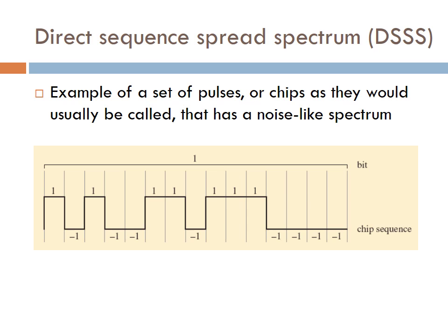Because the sequence spreads the spectrum of the baseband signal, it also spreads the spectrum of the modulated signal. Reception of the data depends on the receiver knowing the codes that are in use by the transmitter and being able to synchronize with the transmitter. I will not explain how synchronization is achieved, but if these conditions are met, the original data can be recovered.